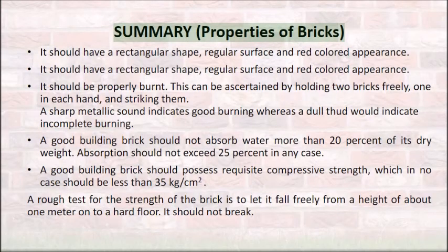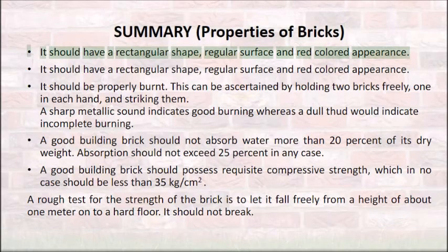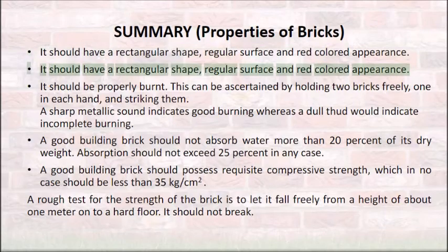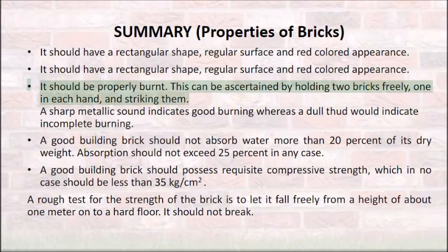Summary: properties of bricks. It should have a rectangular shape, regular surface and red-colored appearance. It should be properly burnt. This can be ascertained by holding two bricks freely, one in each hand, and striking them.